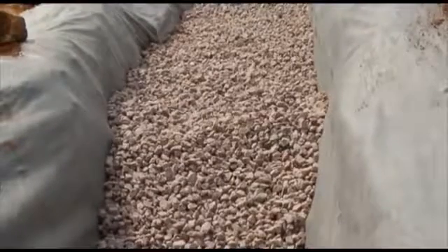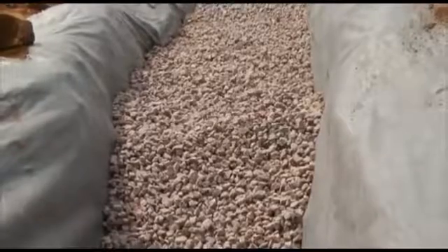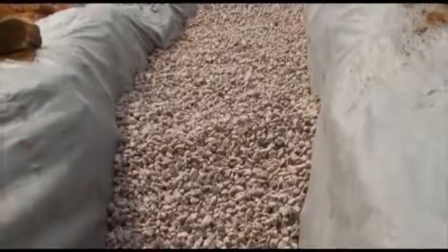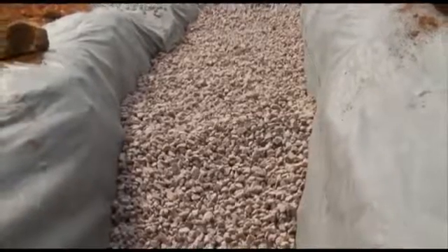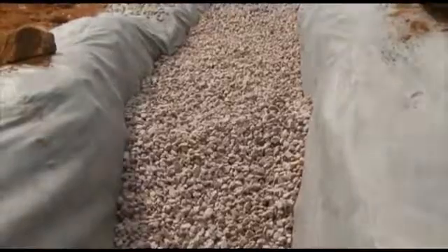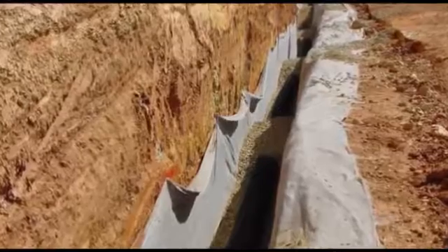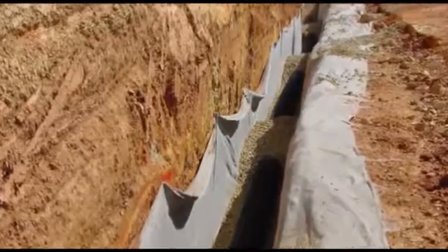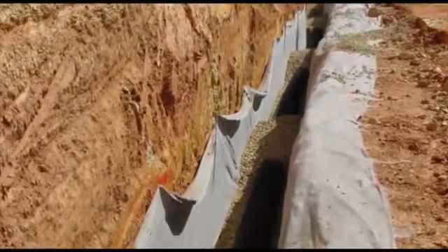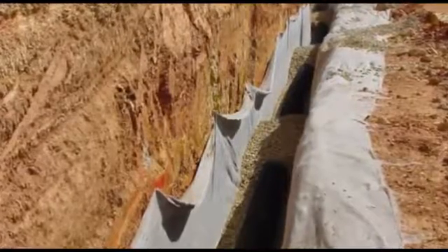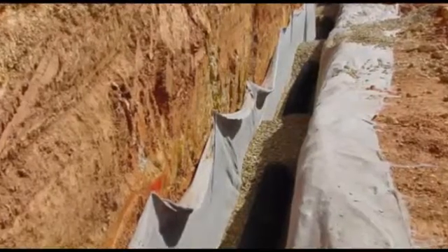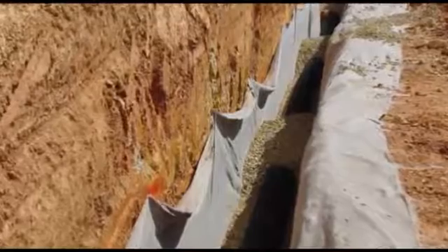As such, the geotextile needs to prevent soil from entering the drain and clogging it. This would mean that the water cannot be drained and will enter the road formation and reduce the road's performance. Engineers need to ensure that the pore size and permeability of the geosynthetic material is appropriate for use with the surrounding soil.